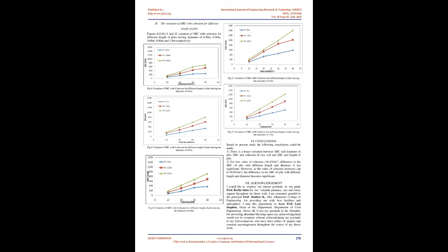of uniform diameter piles. Figure 5 explains the method of determining the safe bearing capacity of a 10 m long, 0.50 m diameter pile in soil having different cohesion from the load displacement curve, as a typical example, and is self-explanatory. Out of the two values, the least one is taken as the SBC. In a similar way, the SBC of all other piles were determined, and the details are presented in tables 4, 5 and 6 for piles of length 5 m, 10 m, and 15 m respectively.